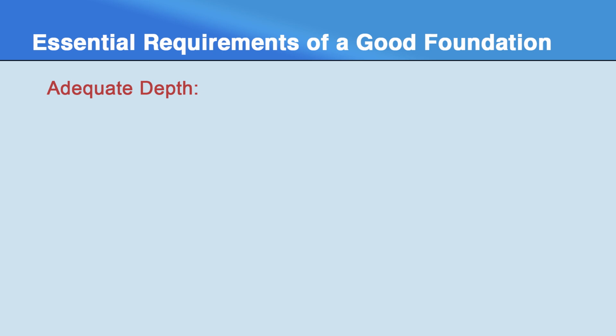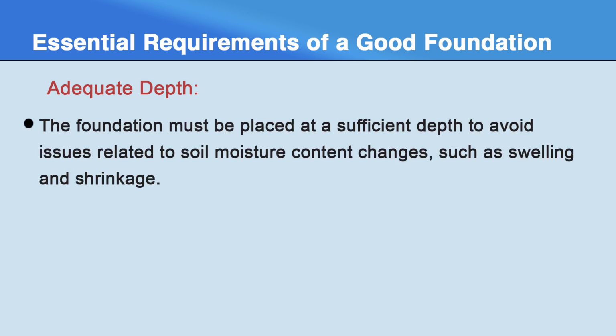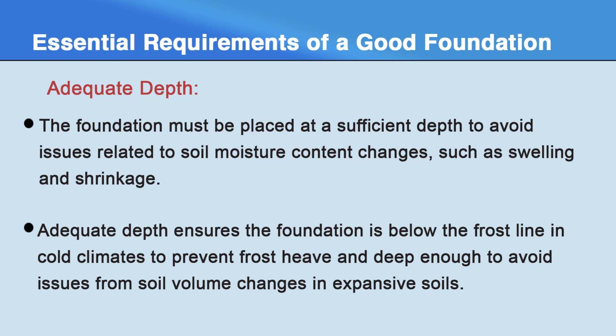Techniques include using reinforced concrete, designing foundations with wide bases and connecting footings with grade beams to distribute loads more evenly. The next is adequate depth. The foundation must be placed at a sufficient depth to avoid issues related to soil moisture content changes such as swelling and shrinkage. Adequate depth ensures the foundation is below the frost line in cold climates to prevent frost heave and deep enough to avoid issues from the soil volume changes in expansive soils.